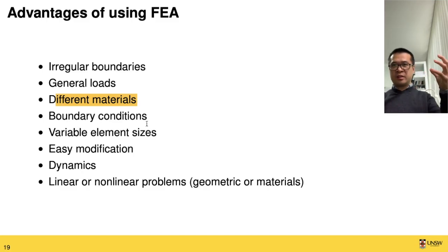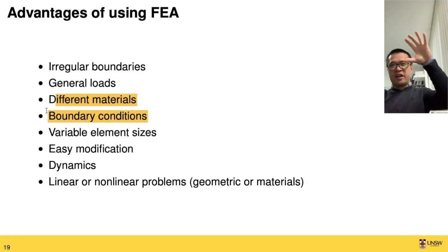You will have boundary conditions, for example, at which point of your structure you are putting the load. If you build a bridge, there will be anchoring points where the bridge is anchored to the ground, and those are the points where the structure is not supposed to move at all. Those will be the boundary conditions built into your design. So when you fix a certain part so it's not allowed to move, how will that affect the overall force distribution?